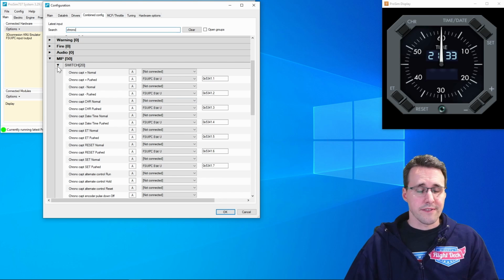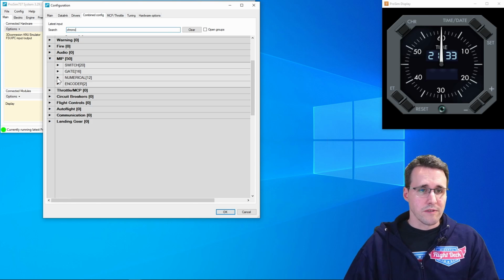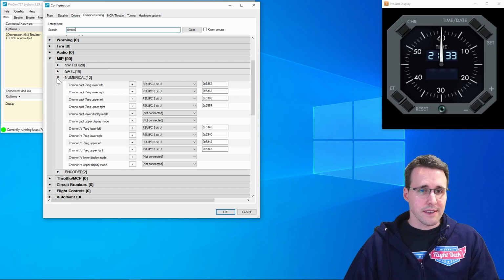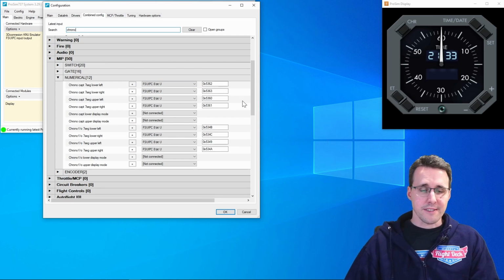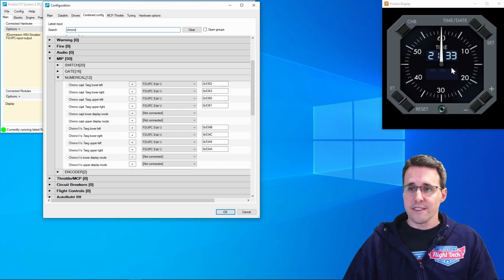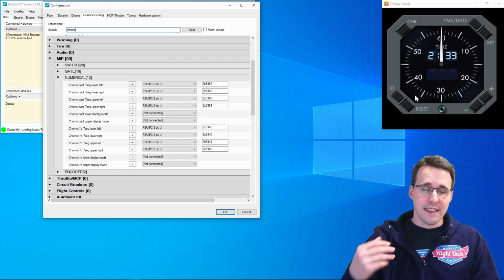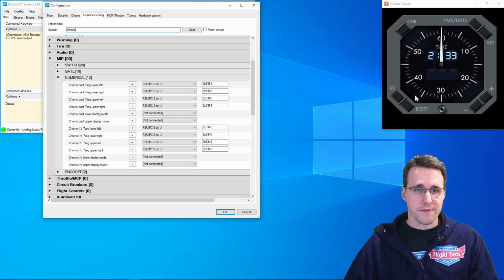And for the 7-segment displays, we can look at the numerical section here, and up here you will find the values for the 7-segment displays. Prosim is dividing these 2 elements here into 4 sections: upper left, upper right, lower left and lower right, and every section with 2 numbers. And to transmit all these numbers, an 8-bit unsigned offset will be enough.